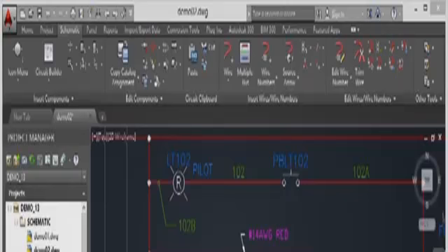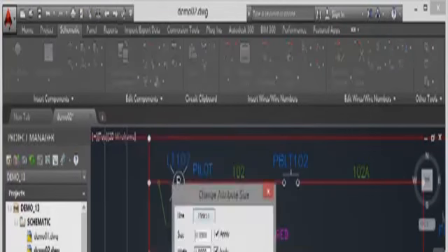The size of the attribute text that you've got on your AutoCAD electrical drawing is controlled by your project and drawing settings normally. However, you can edit that within the drawing itself. So let's have a look at how that works. Up until now, I've recommended selecting the component, right-clicking like so, going to the attributes, and you'll notice there that I can change my attribute size there.